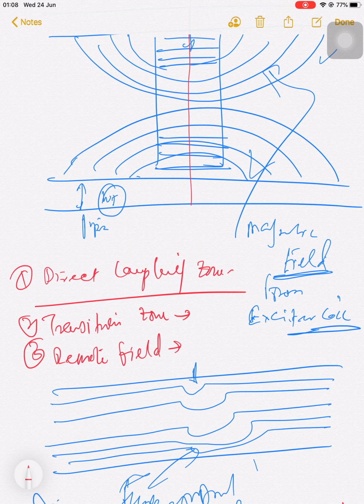So how is detection of the flaw done? Where there is no flaw, the phase of the receiver signal with respect to the phase of the exciter signal is directly proportional to the sum of wall thickness within the inspection area. When a flaw is met, multiple changes will occur. A flaw can be detected. A flaw may be corrosion pitting, crack, or erosion thinning.